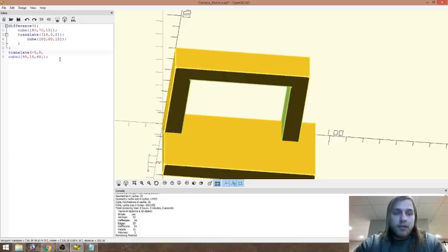And then for the Z direction, I'm going to use -12.5. Now, that seems like kind of an arbitrary number, but it's really not. Where that's coming from is we have 40 millimeters from this point to this point, and we have 15 millimeters, that's the width of the perch. So if we take 40 and subtract 15 from it, we then need to divide it by 2 in order to figure out how far to move this.